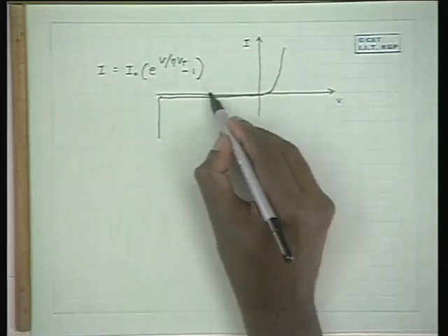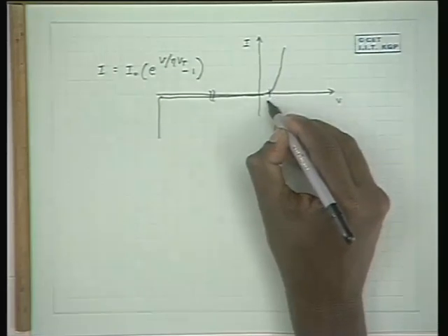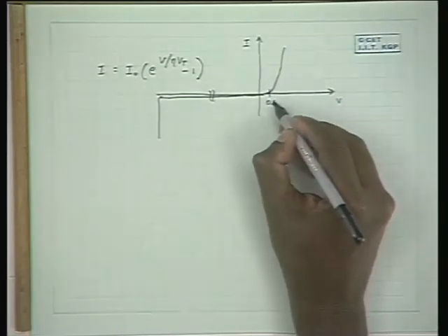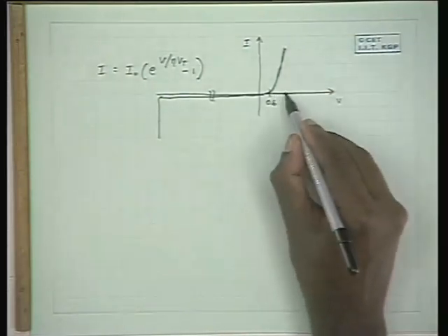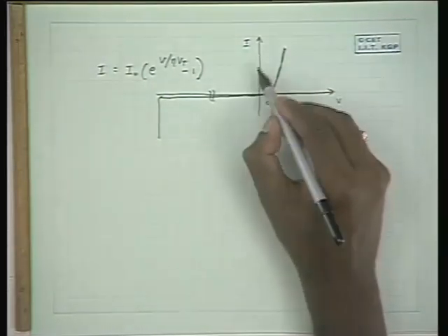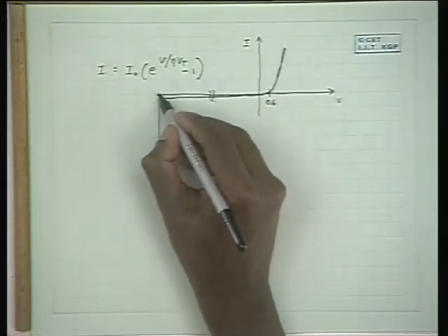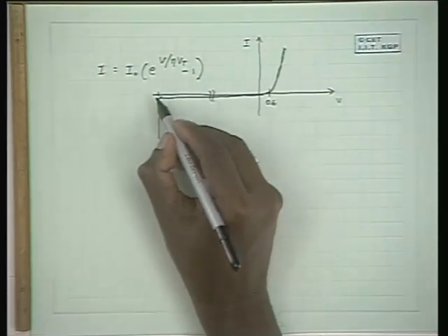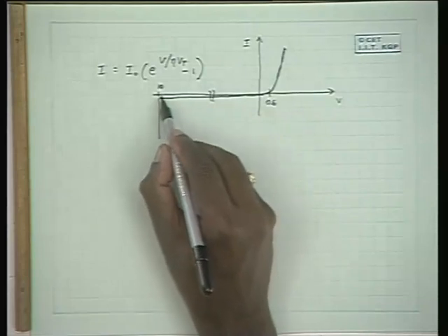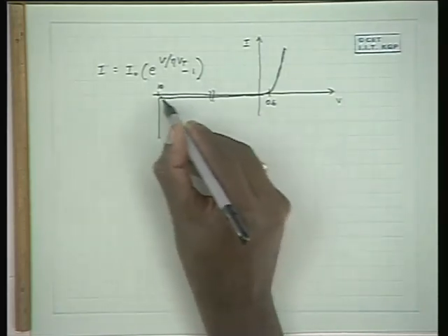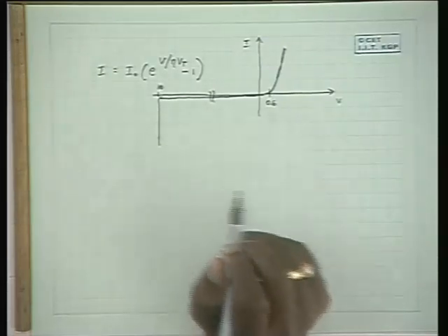Typically, this is the plot of a silicon diode. Above 0.6 volts, with a small increase in the voltage across it, the current increases, whereas in the reverse direction, up to a high amount of voltage, depending on the construction, it may be 10 volts or 20 volts or 5 volts, the diode breaks down, and so there would be a huge amount of current again.